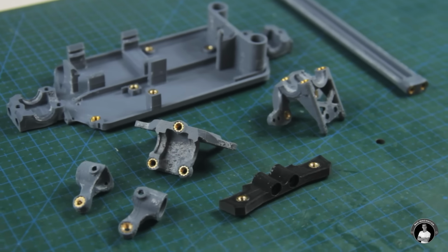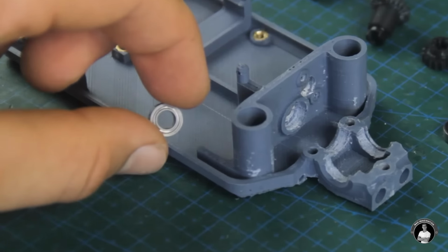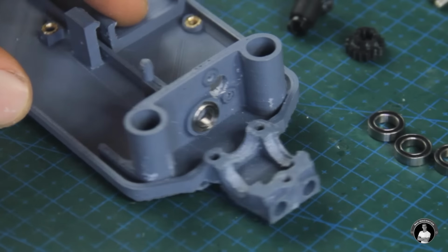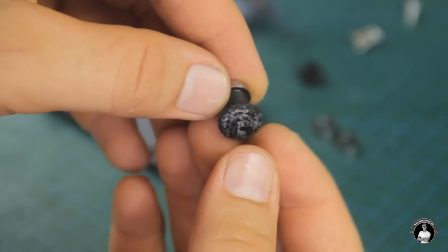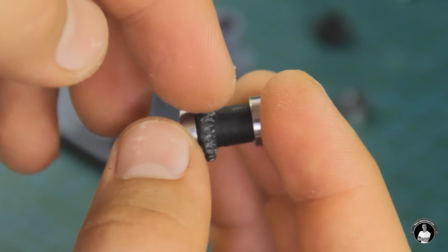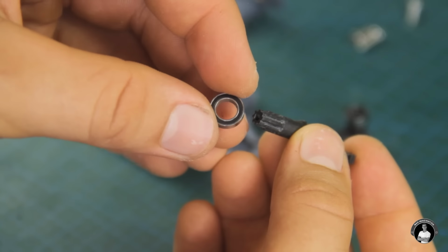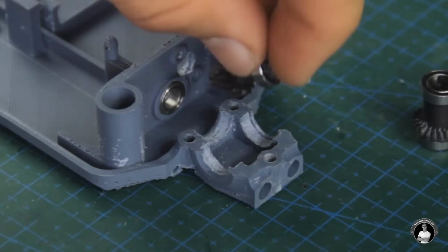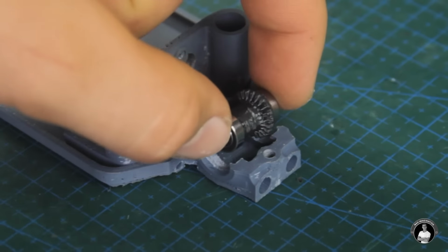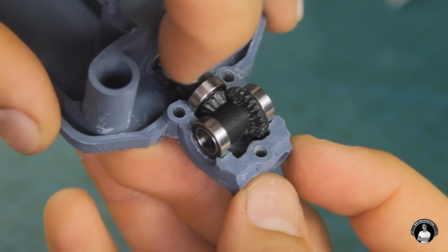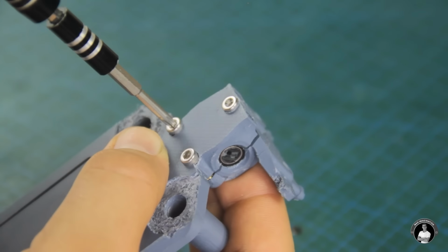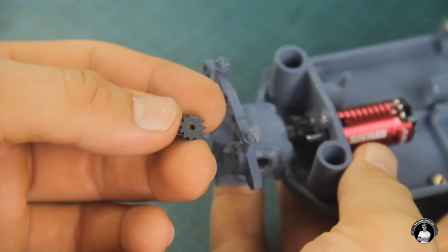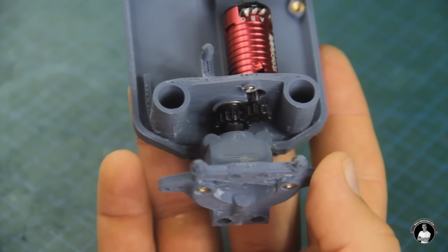Now we can begin installing the first part of the drivetrain, which is the rear drive mechanism. Let's pop in a 9mm bearing into the chassis, which supports the drive shaft. Then attach the 2 10mm bearings onto one of these beveled spur gears without a differential, followed by assembling the rear drive pinion gear with a bearing and spur gear attached with which the motor makes contact. We can then install it and the spur gear positioned with orientation in mind. Afterward, let's secure the rear gearbox housing together and install the brushless motor with its pinion gear to wear in the bevel gears inside, which will help make the shaft turn with ease.